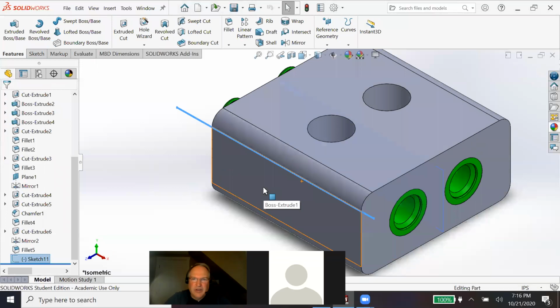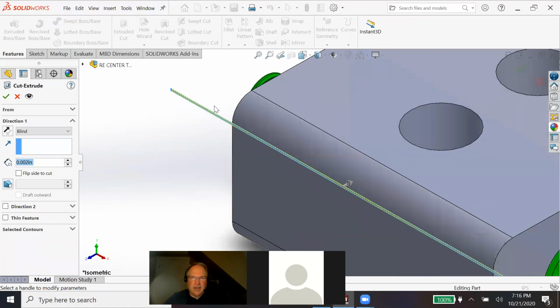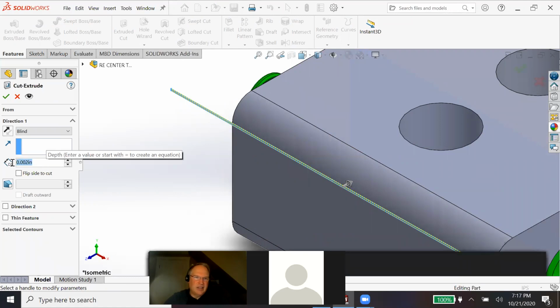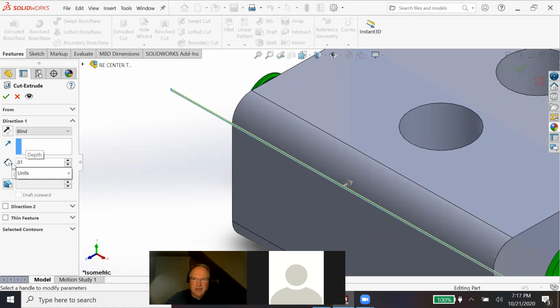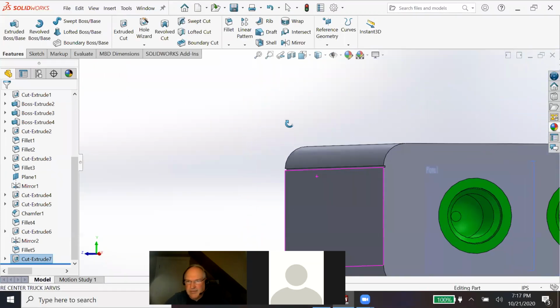And when you cut it out, now notice, because I'm cutting it away, I didn't care about how far out it came. A lot of people are trying to cut it and make their rectangle starting right on the edge. But remember, whatever we extrude or cut out of there, it doesn't matter if I cut it out of space over here, it makes little difference. And you can see that the distance going in is going to be minimal too. I want to say 0.01 deep, 1/100th of an inch deep. And it leaves that little tiny groove right through there.